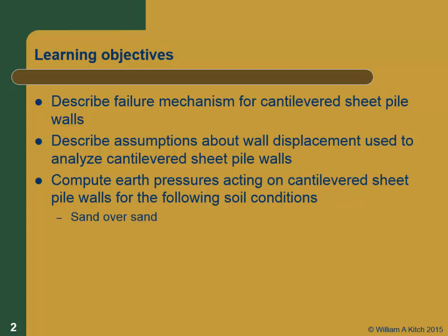And then I'll go through the methods for computing earth pressures on cantilevered sheet pile walls, where we have sand over sand, or cohesionless over cohesionless soils, where you have a cohesionless soil over a clay soil, and where you have clay over clay soil. This is the first time we'll really talk about design of walls with clay soils behind them, because lots of times we're installing these in places as cut walls, and that's the material that's behind it, and we won't be able to do anything about it.